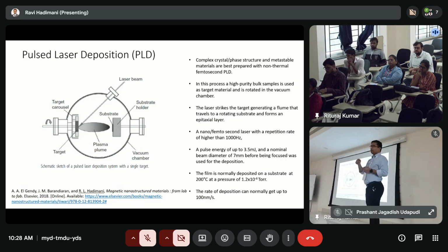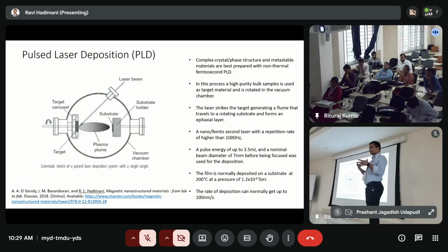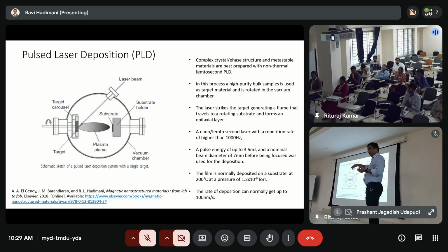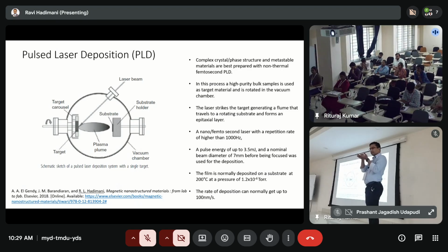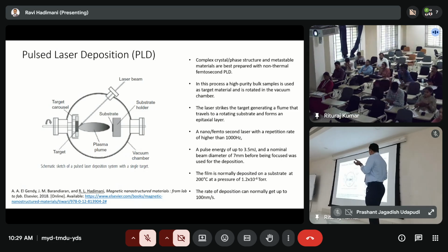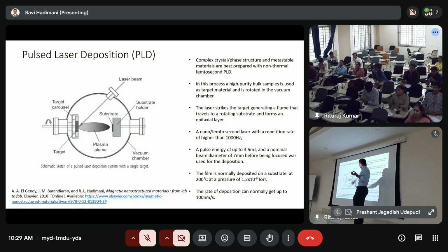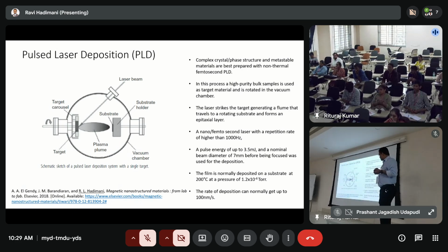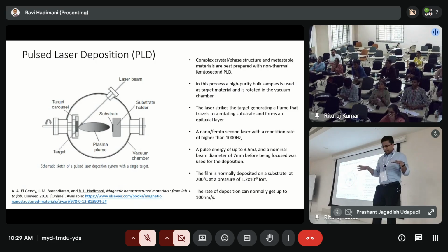When they go up and come down, they release a phonon. A phonon is nothing but vibration. The phonon is what results in heating. So the vibration, the phonon it generates in the material, heats that material in that place. And this is very local. We're talking in terms of a few microns. That's how a nanosecond laser works. The phenomenon in a femtosecond laser is slightly different.